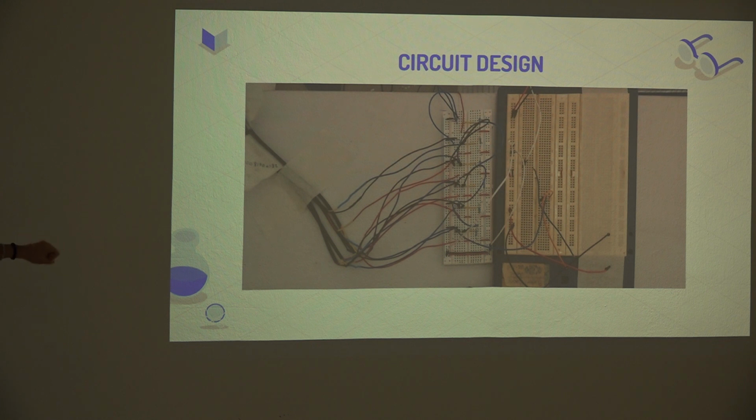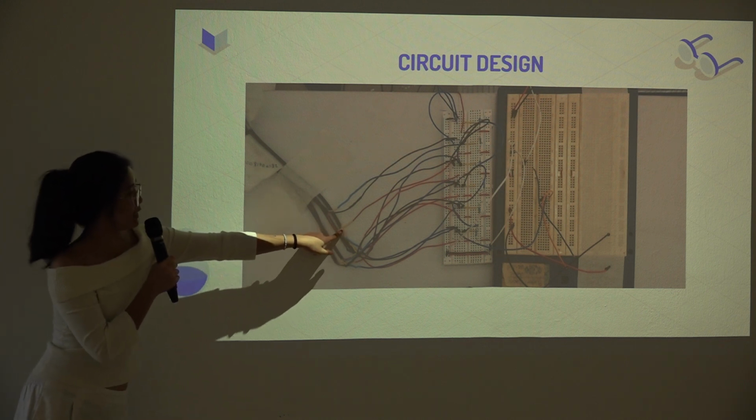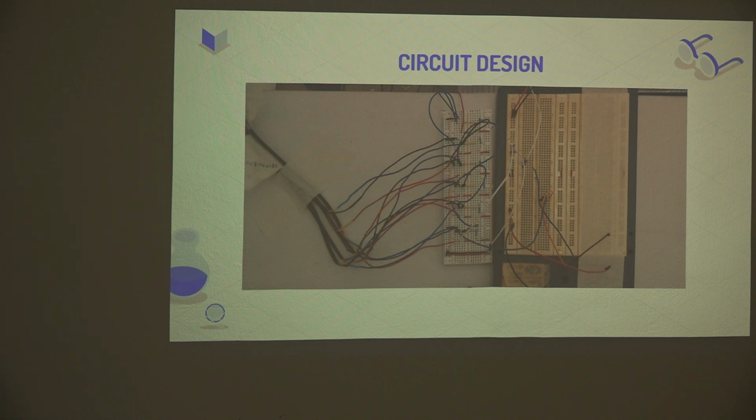You can't really tell from here, but these yellow parts are additional insulation layers that we have put on top. When these sensors came in, the wires they had were stranded wires, which wouldn't be very efficient to place into the breadboard, and the results coming out from the program might not have been as accurate. That is why we put into use our soldering skills and soldered solid wires onto those stranded wires, and then connected those solid wires into the breadboard.